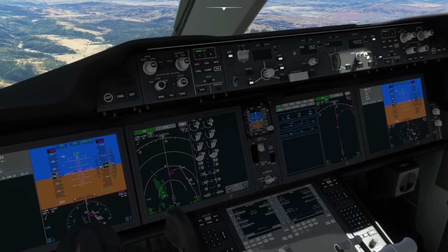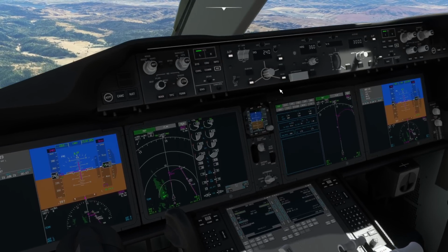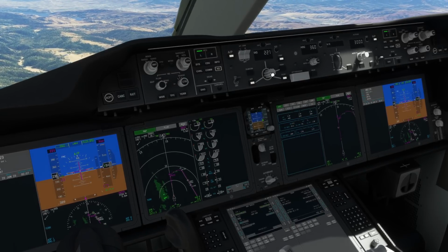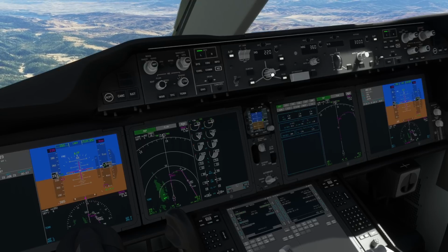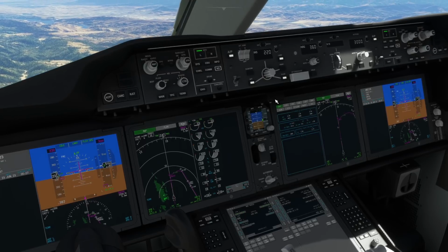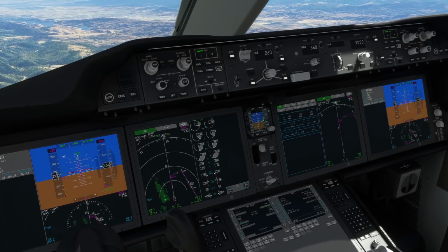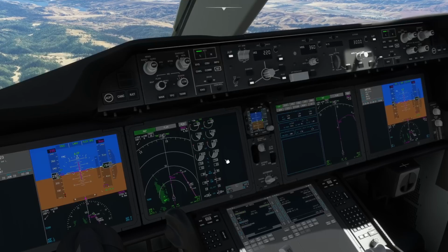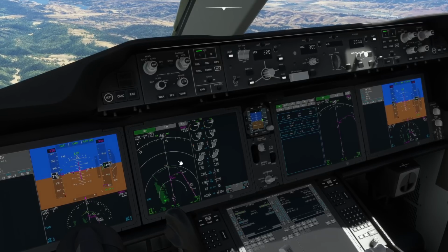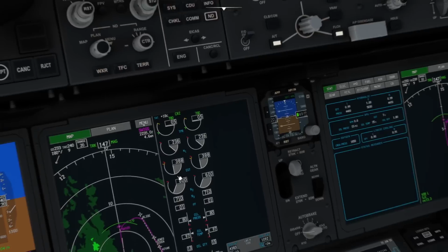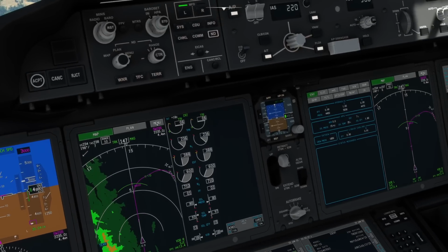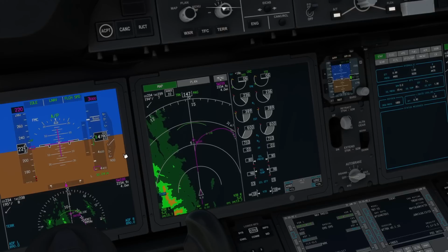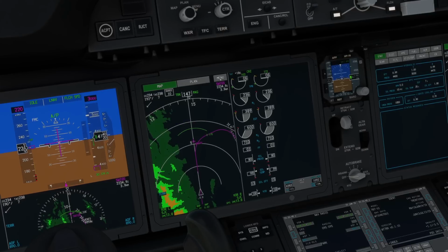So if we come back down to 3,000 feet now, we'll do a flight level change to get there. We'll also ask the aircraft to slow down to 220 knots. So we'll use spoilers to cause the aeroplane to slow down quickly, and then we should see these patterns change. So there comes the green banana, as they call it. So let's pull the range in. And you should see this changing as we descend. Yep, there it goes.